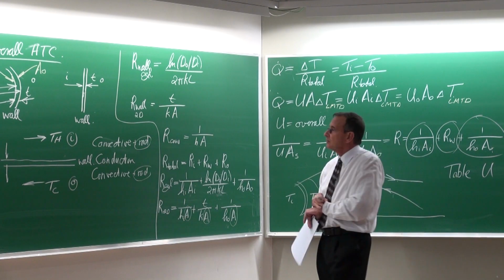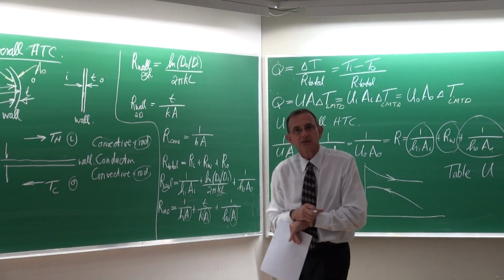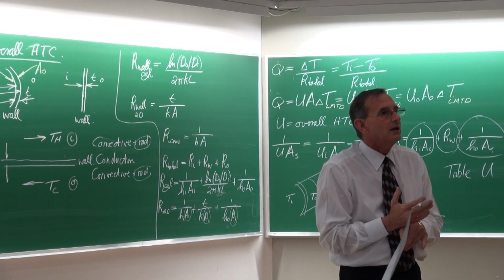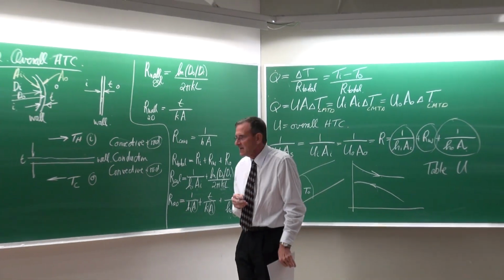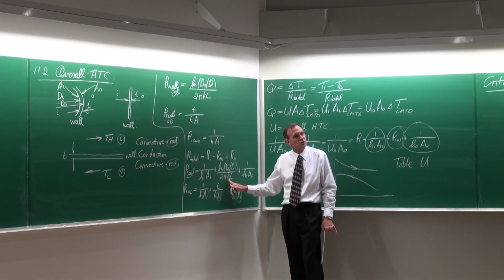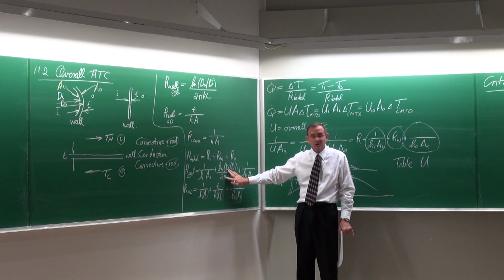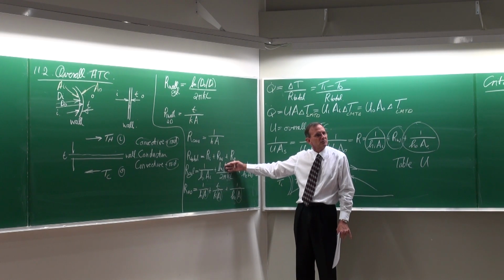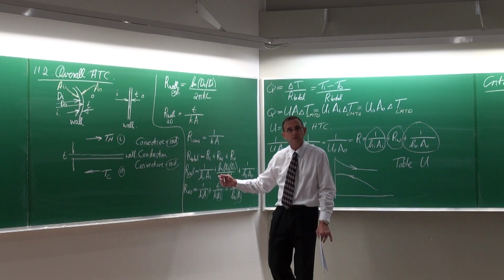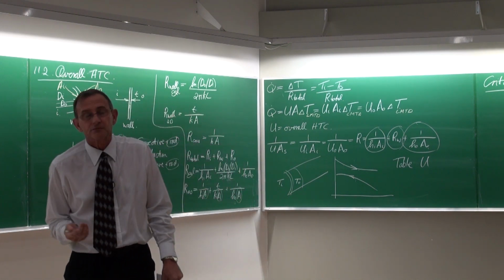If I would say, well, many car radiators are being made from plastic, and that's a good thing. Would you agree with me or disagree with me? So most people would say, no, that doesn't make sense, because when you use plastic, the thermal conductivity is very low. Do you agree? However, with plastic, they can make very thin walls. So this is going to win by far. So plastic heat exchangers with thin walls are being used a lot in industry. They are very effective heat exchangers. Thermal conductivity doesn't play a role. Okay.